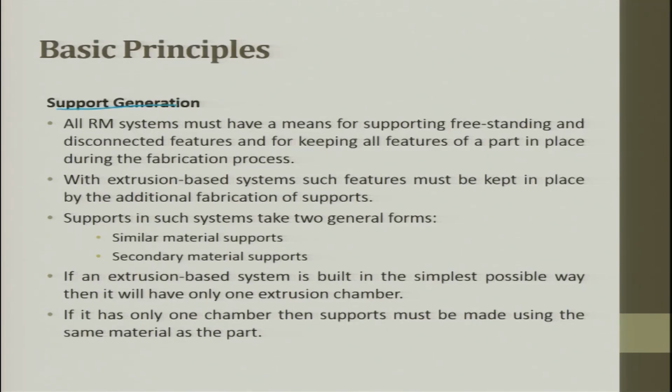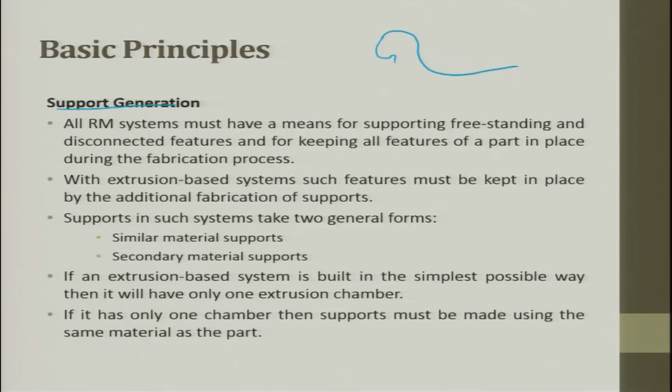Support generation, this I was trying to tell you: you have a free hanging surface. This free hanging surface has to be supported. For example, if you want to make an object like this, okay, this fellow has to be supported from here.